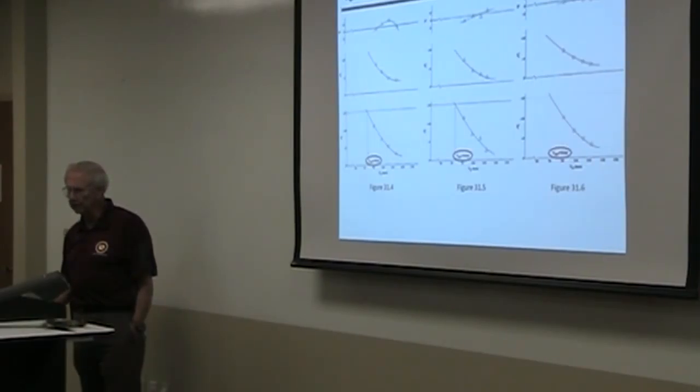You can see what's happening with aileron deflection. As we slow down, we're going to start the test up here, and as we slow down, we notice it requires more aileron deflection. This is rudder deflection down here, and of course, in this case, we have about 25 degrees of aileron deflection available here, and we have 15 degrees of rudder deflection in this case.